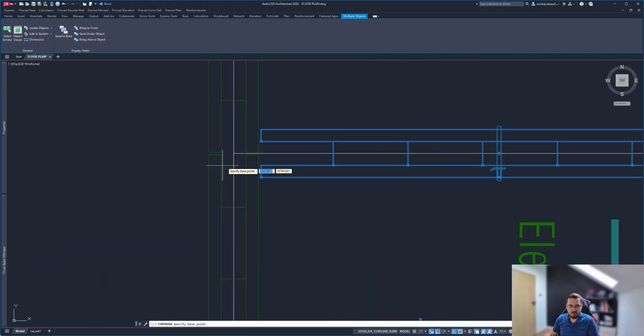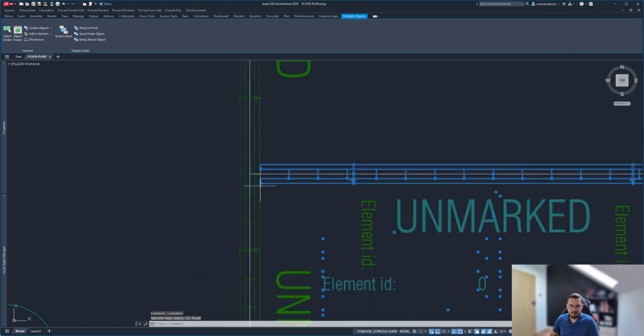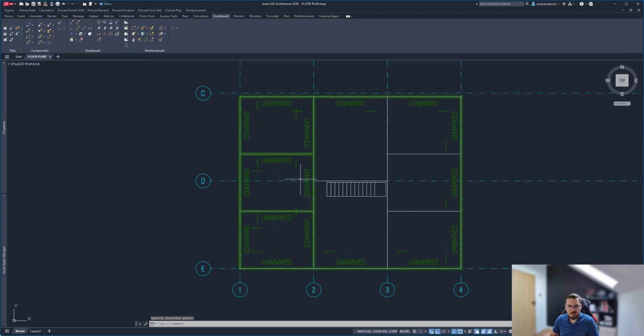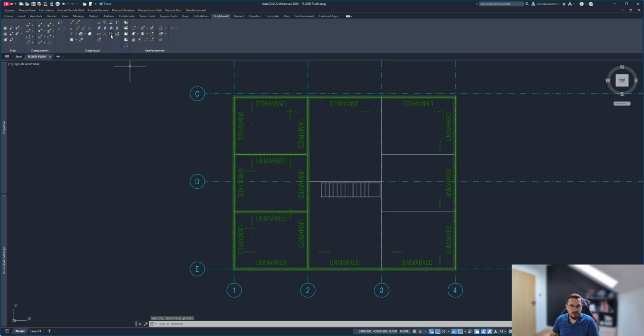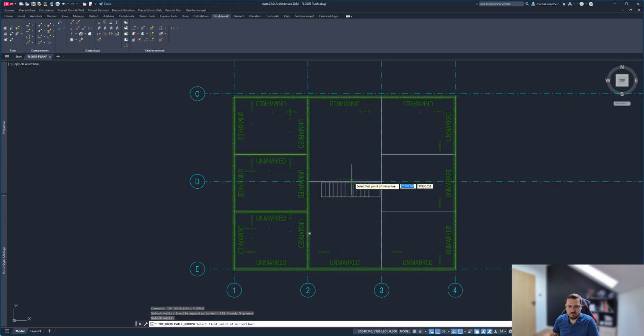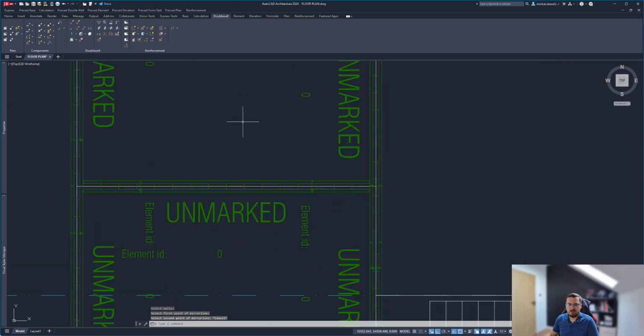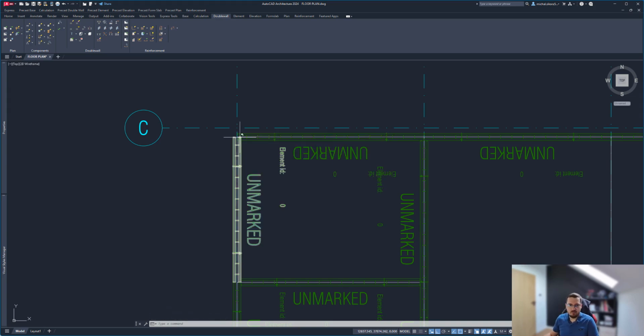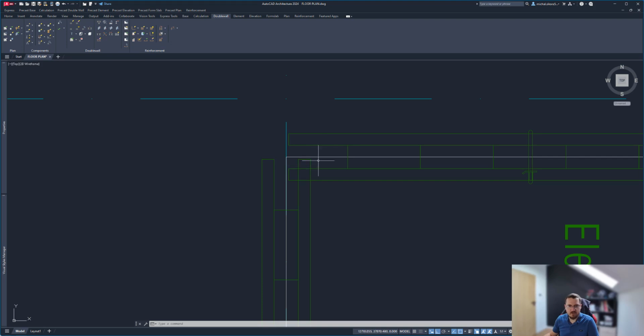And with that, I can also copy the walls with standard AutoCAD commands, so I don't have to draft everything manually. And I can also use a mirror tool, so I can copy those walls to the other side, right? But maybe before I do that, before I copy those, let's focus on actually editing those walls slightly. So what I mean by that, for example, here, that's the start point and my end point of the whole placement of the external double walls.